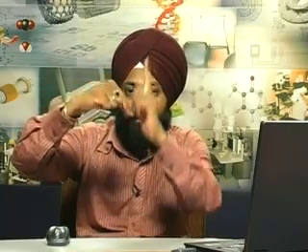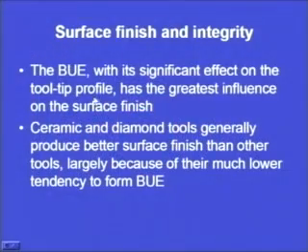Now, suppose this is the tool tip and there is some material getting deposited on the tool tip. Then the angle with the vertical line which has been generated will get affected, and this effect on the angle will affect the machining behavior. So, the built up edge, with its significant effect on the tool tip profile, has the greatest influence on the